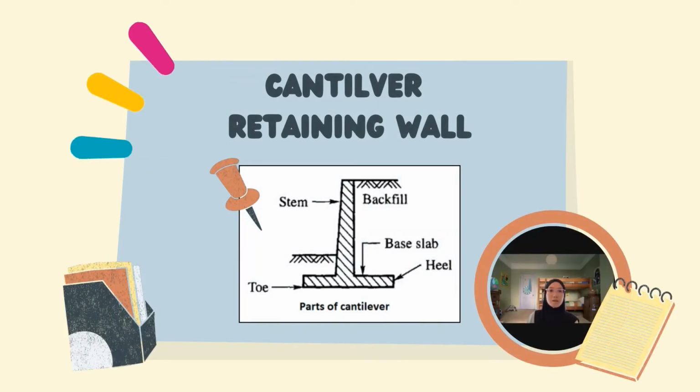The cantilever retaining wall is a construction that is made up of a vertical cantilever that extends from a big stiff foundation slab. According to the Eurocode, the design of reinforced concrete retaining walls consists of two fundamental stages, namely stability analysis and section design. The stability analysis highlights the principal force operating on the retaining wall, which is the lateral force caused by ground pressure, which can cause it to topple, slide, and settle.